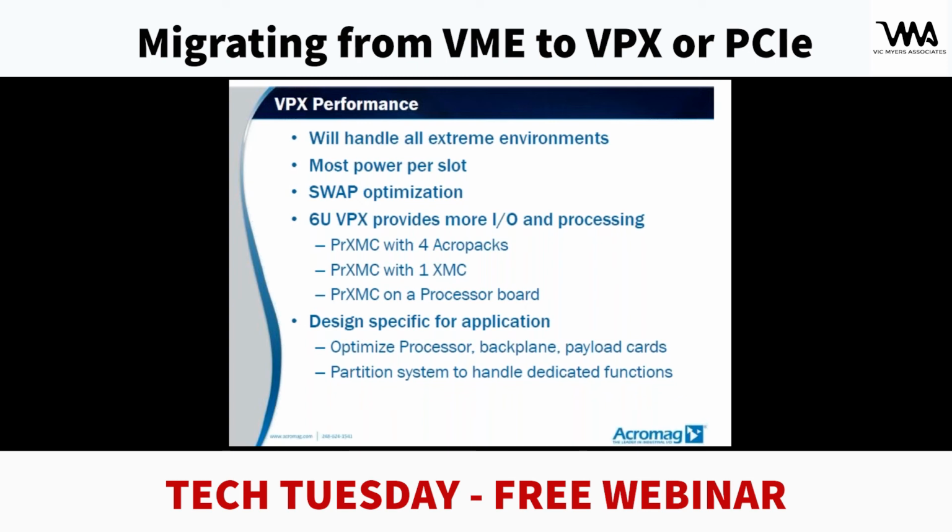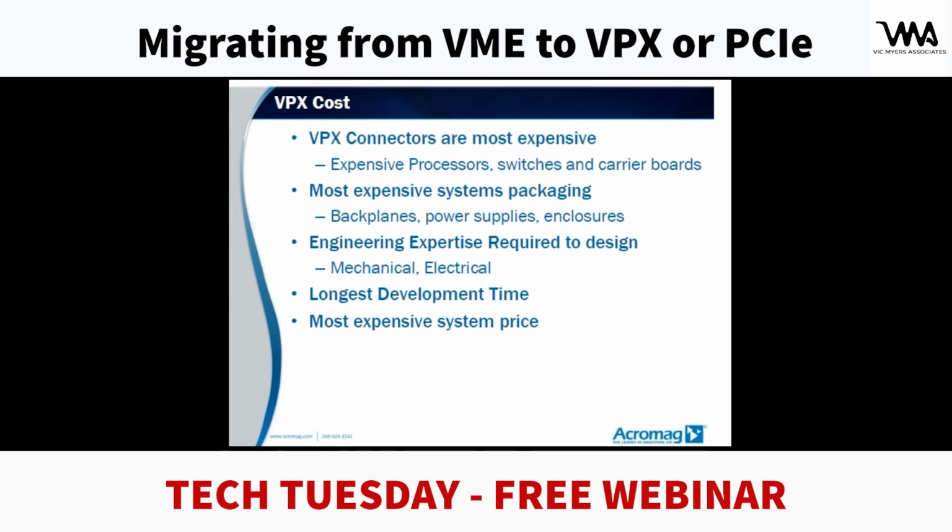Performance is optimized for the application when it comes to VPX. So you can optimize processor, backplane, payload cards. You can partition the system to handle dedicated functions. The cost of VPX is typically tied up in the connectors. These are the most expensive connectors on the backplane. Therefore, all the processors and the switches and the carrier boards that require the mating connectors, those add cost and